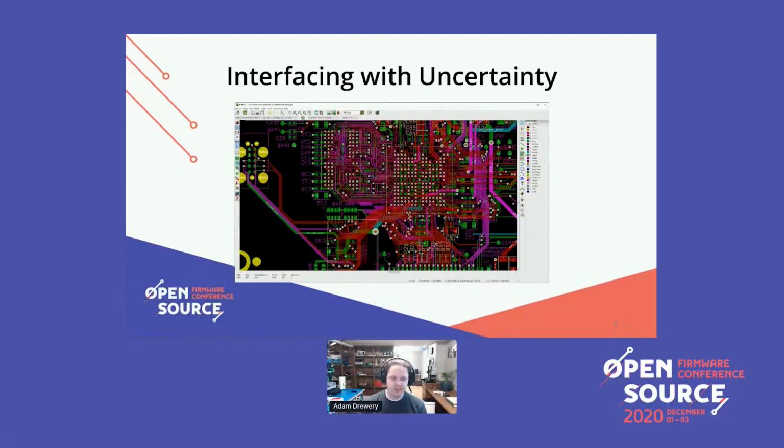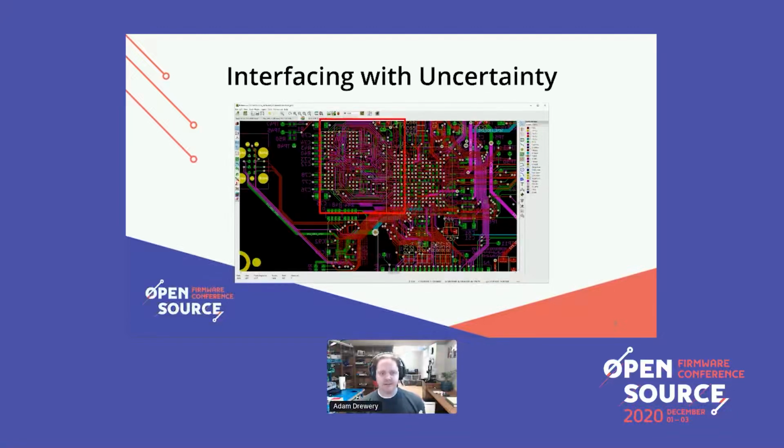Now, in this particular image here, these squiggly lines, this part's super important. These are DDR3 RAM layout lines, comms lines. This runs at about 800 megahertz. What this ultimately means is that within 2 nanoseconds, or 0.000000002 seconds, 2 bits are going to be clocked back and forth between those two devices. That means that those lines have to be within a few tenths of a millimeter in order to guarantee that everything gets there at the right time.